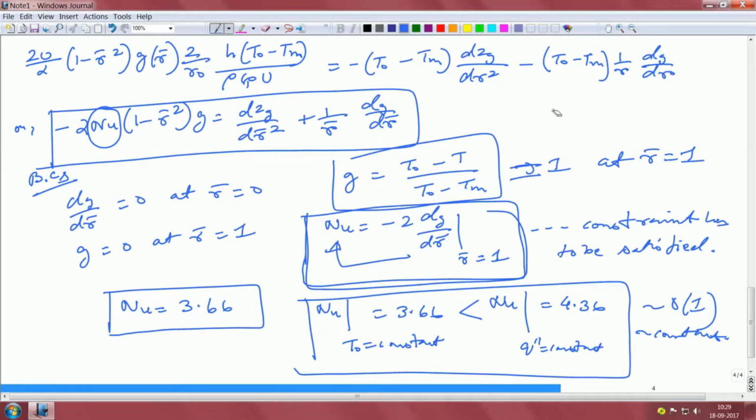In all of those cases, you will observe that the Nusselt number value for the uniform heat flux within a particular family is always higher than the corresponding isothermal wall temperature, right. Okay. So, that is what you will see always for all the cases. And for fully developed flow the circle shows the largest value of Nusselt number, right. Whereas, the same thing is valid for the isothermal wall also. For any other cross section, you actually have a reduction in Nusselt number, okay.